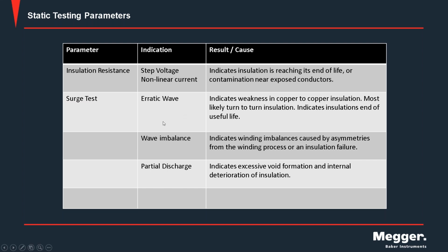Surge testing, we're basically impulsing on the winding some energy, and we're looking at how that winding is responding to that energy. This kind of a ringing, it's almost like a resonance test, if you will, like a ring in a bell. We're kind of looking at, are there any cracks in our bell? In this case, are there insulation weaknesses that the surge test can identify? And that's specifically looking at the turn-to-turn insulation that we talked about at the beginning of the presentation.